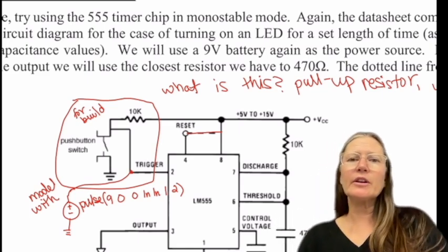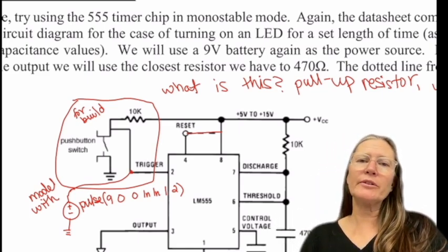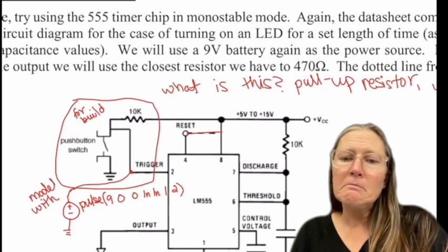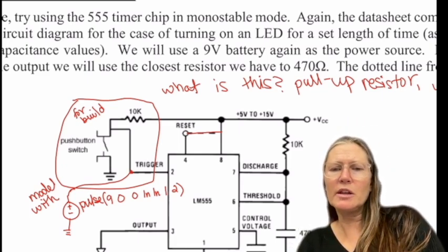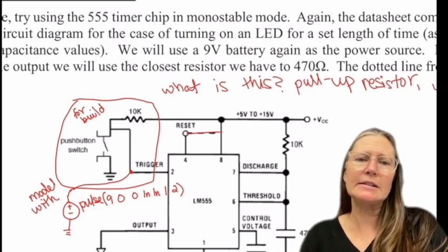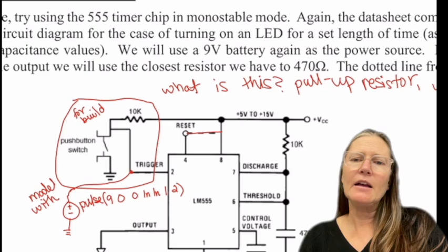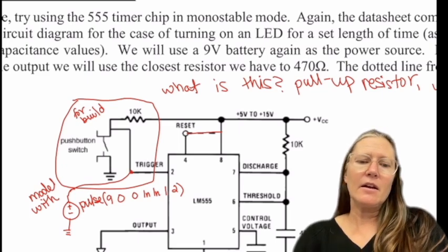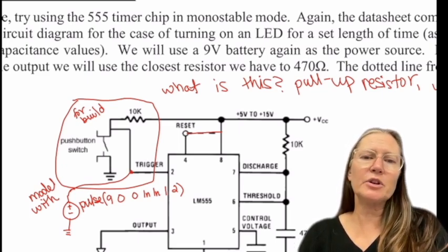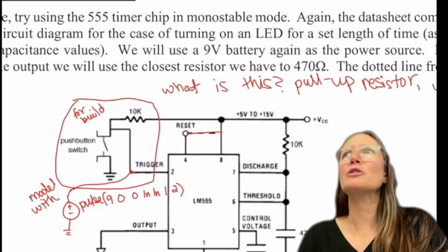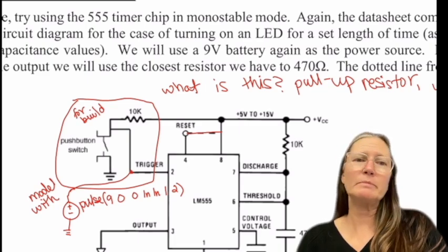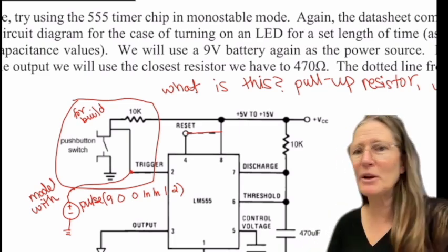So you can see that it gives you a pulse, and then once it's triggered, it basically stays on for close to 5, or let's see, I guess it starts at about 1 and then goes to 5. So it's about 4 seconds. And then for 47 micro, you can see it's much shorter. So make sure you can do it and play around with that for a minute.